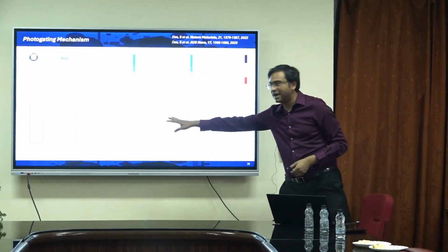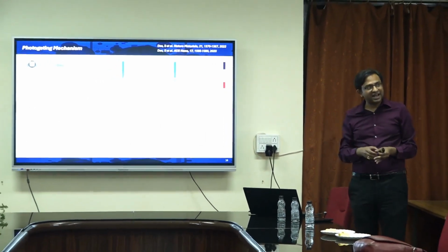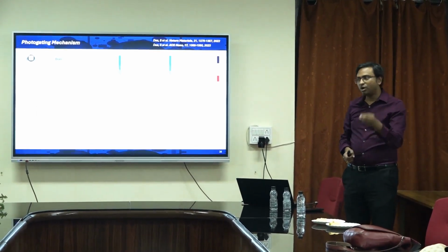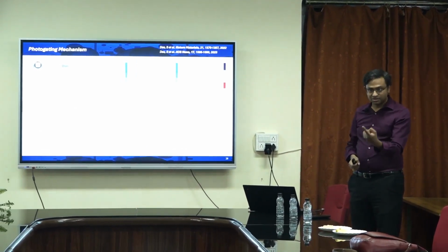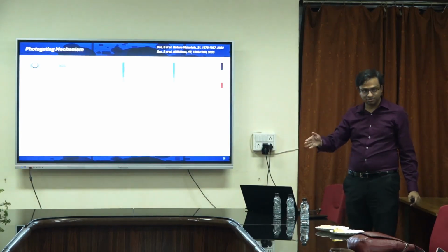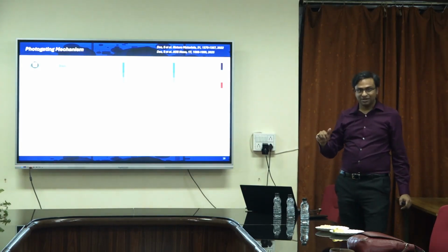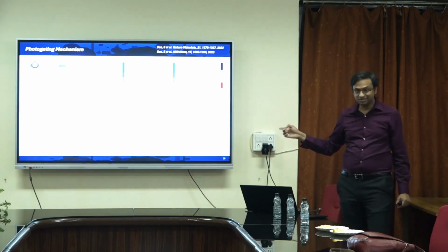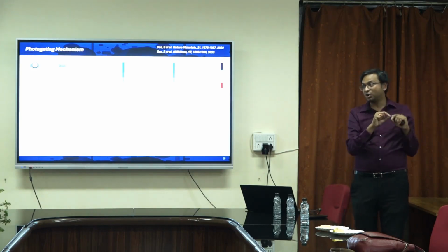So don't go into all these band diagrams and stuff. This will take a long time for me to explain what's going on. But the basic idea is that what I could do with voltage to trap charges, I could also do by shining light. Right? But now this is non-volatile. Generally, in the response of a photodetector, once the light is switched off, the response goes down. Here, it doesn't happen like that. It stays, right? So you integrate the memory automatically with vision in these devices, by combining a memory element with the photodetector.